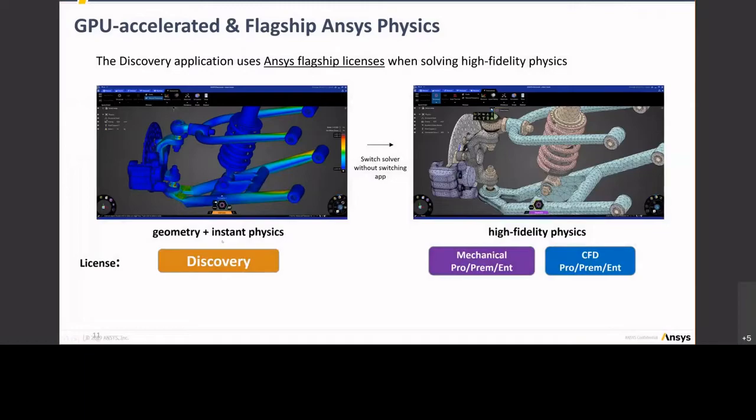So when I say GPU accelerated simulation, I'm sure you probably all know on your standard machine, you have a CPU, central processing unit, and a GPU, graphics processing unit. We specifically support NVIDIA GPU graphics cards. A graphics card has 500 cores or 1,000 or 2,000 or 4,000 cores, whereas your average CPU will be 2, 4, 6, 16, some up to 64 these days, so you can see that literally the number of cores in a GPU accelerates away from what's available on CPU.